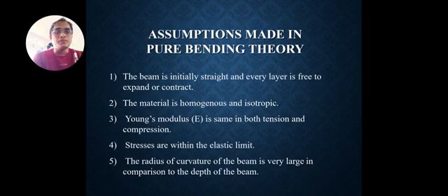Assumptions made in pure bending theory. The beam is initially straight and every layer is free to expand or contract. The material is homogeneous and isotropic. Young's modulus E is the same in both tension and compression. Stresses are within the elastic limit.